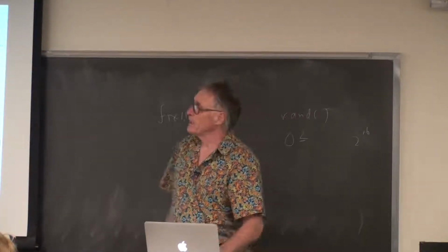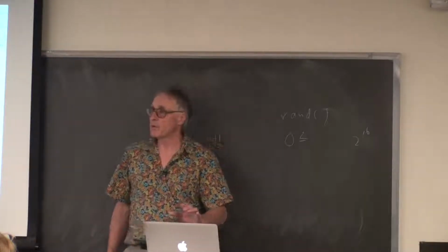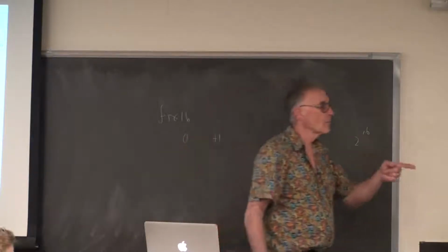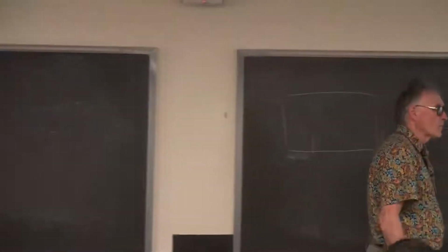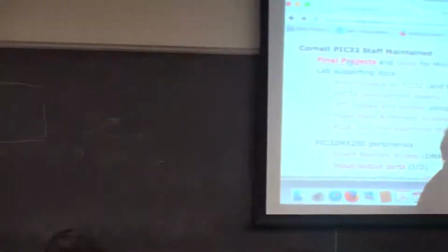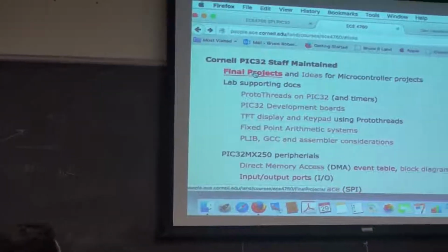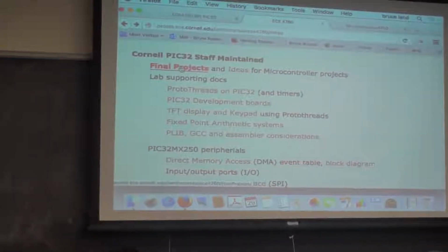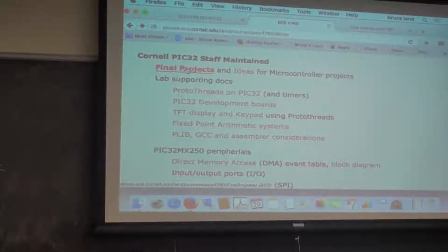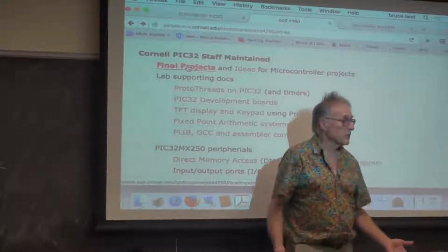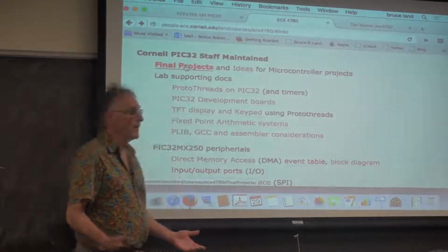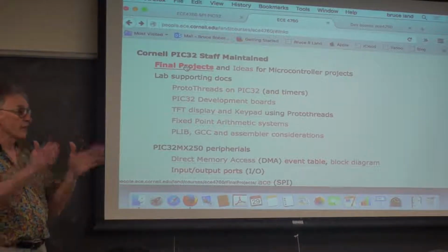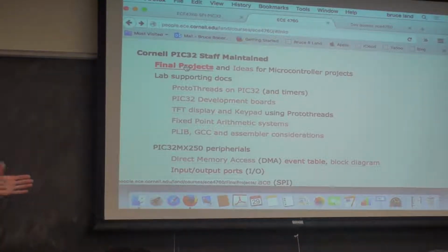But again, any lingering questions on Lab 3 at this point? I have a question about the audio. When we build our tones that we want to play, you create a table. But then how do you do that in memory? Is it just an array? A table? It's just an array. Right. So if you have a named array like sine table, the name of an array is a pointer to the array. Okay. So you can use that directly as the source of a DMA burst. Okay.